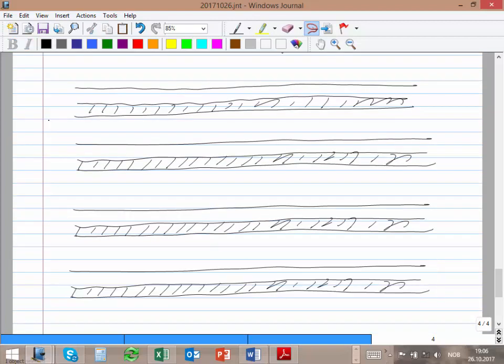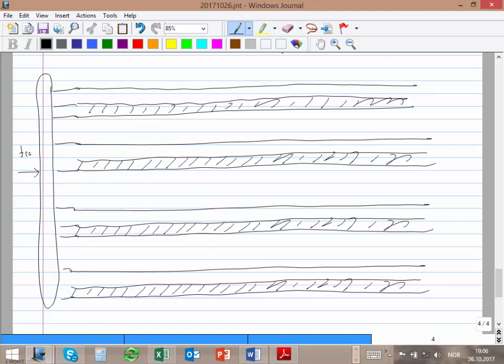And you put here a common entry from a common manifold that is going to give fluid to all of them, and here I have the production from the field. In that way I have a lot of volume and I can receive these big slugs, and I have no problems with my separator.